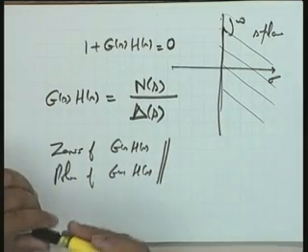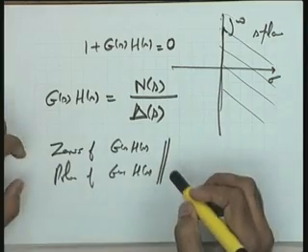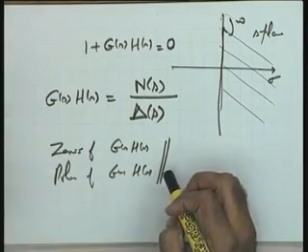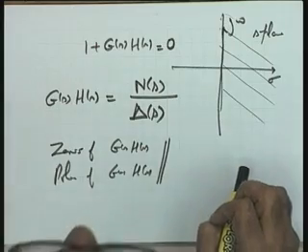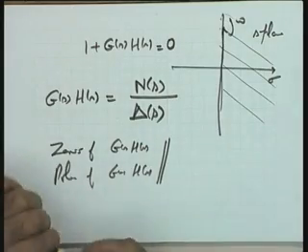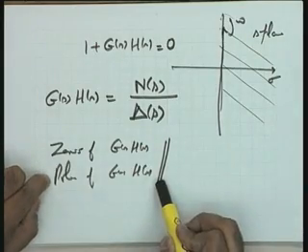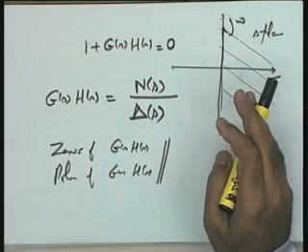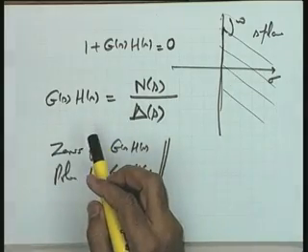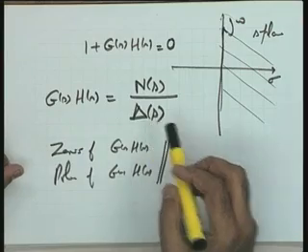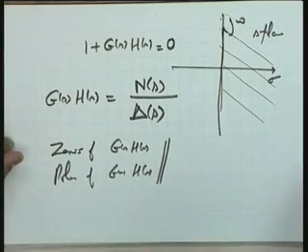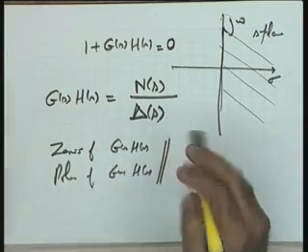This is nothing to investigate, this is data given to me. This point may be stored in your memory, particularly that the poles of G(s)H(s) are known to me. So you see that if the poles of G(s)H(s) are in the left half plane, the system is open loop stable, and if some of the poles of G(s)H(s) are in the right half plane, then the system is open loop unstable.